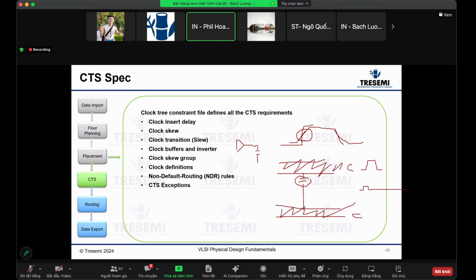A lot of times people prefer this over one of the other options, which is shielding. You put a ground or VDD here, so it's really a capacitor to ground, and there's no spacing issue with the signal. You have shielding between your clocks and your signal by having a ground in between.